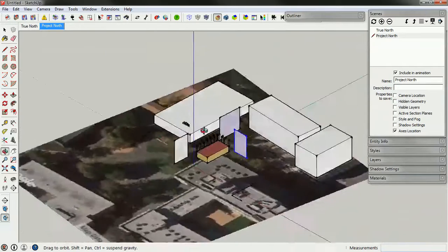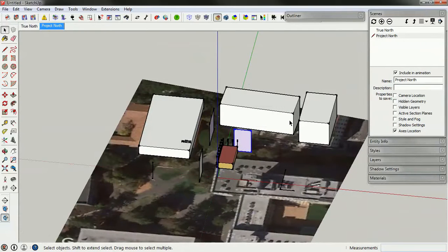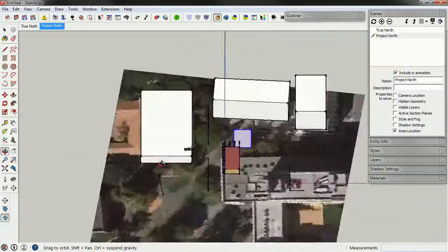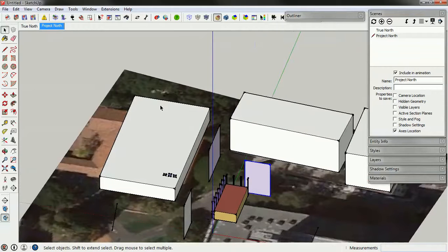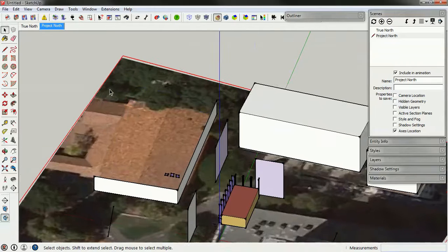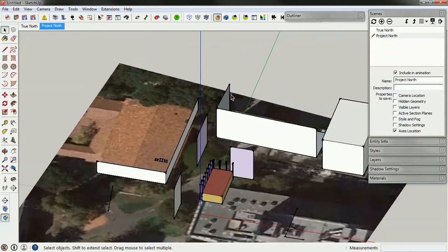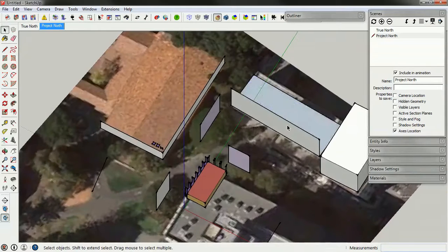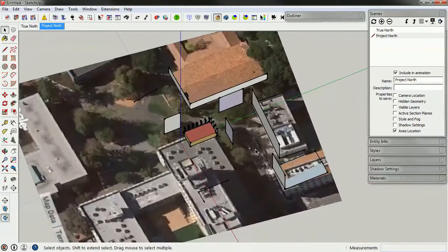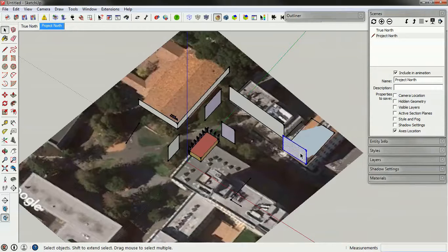Now I do want to make sure that these are all in shaded geometry. And in fact, there's a lot of these faces I don't need. It just will add to the runtime. So I'm going to delete all the faces I don't need from these shading objects, including the tops, the back sides. All I really want are the front sides like that. And I'm going to delete these guys too. Maybe this one as well. So it just adds to the runtime for the run. Actually, no, I'm going to just take this whole thing out. I don't think I need it.